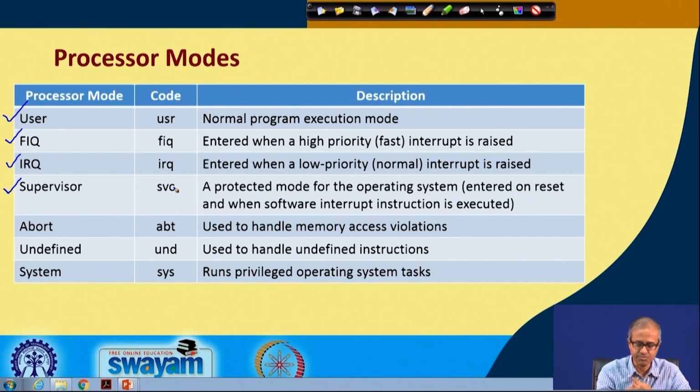Now, the supervisory mode or SVC, as mentioned here, is a protected mode, and this mode is required only when there is an operating system in your implementation. Well, in all embedded system applications you will not require this, but in a system where there is really an operating system and you need some protection, you need to have this mode of execution.